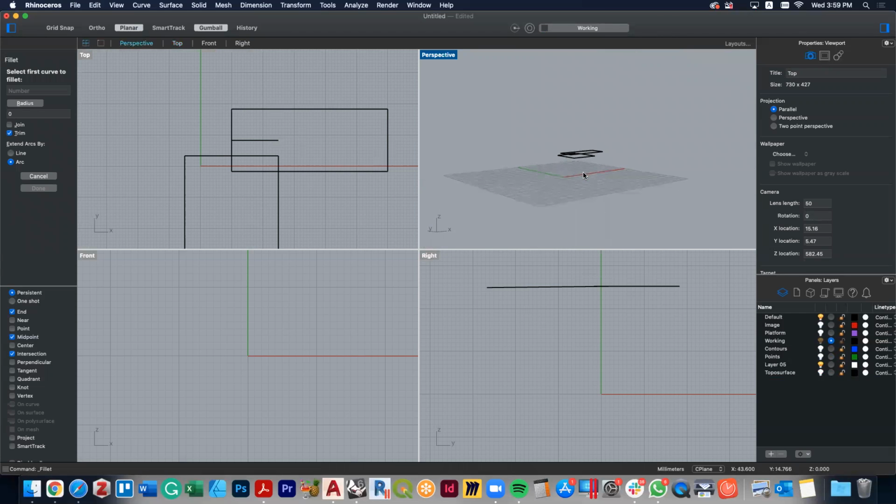One of the things that Williams talks about is the idea that the slopes are at 1:50. Because this distance here is 5 meters, the side slopes are at 1:5. I'm not actually going to make it that way. I'm going to make the side slopes 1:3. It's important to remember that, because I'm different from William. All of the embankments are at 1:3.